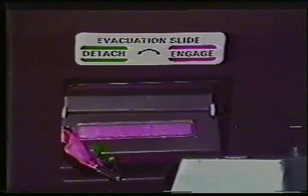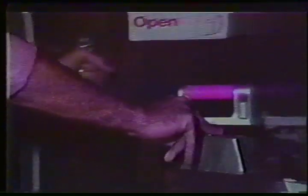To open the door in normal operation, ensure the lever is in the detach and lift up on the operating handle. The door will move outward and slide forward along the fuselage. To close the door, depress this black gust lock button. Slide the door back and return the operating handle to its original position.